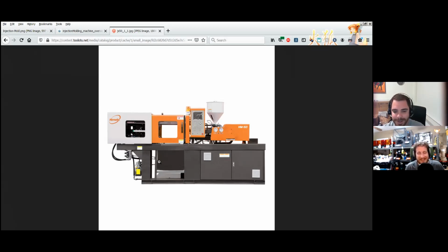Yeah, so here in the middle, right below that door, you would just throw a bin and let this machine go. And I don't know, the cycling time would depend on how big your parts are. But say, every 10, 15 seconds, it'll shut. You hear a sound as the hydraulic pressure increases, it would shoot that plastic, and then it would open up again, and your part would either drop or be ejected out, and the bin will just fill up over the course of a couple hours. And that is high volume manufacturing, which 3D printing is not.